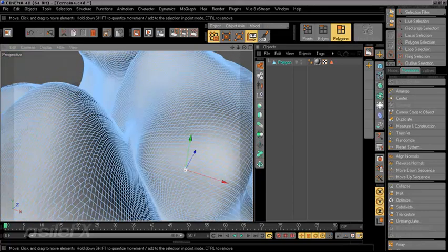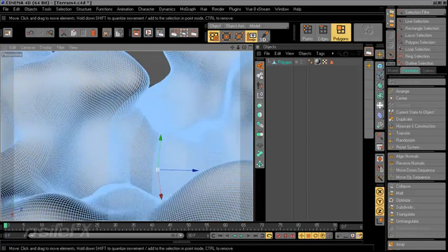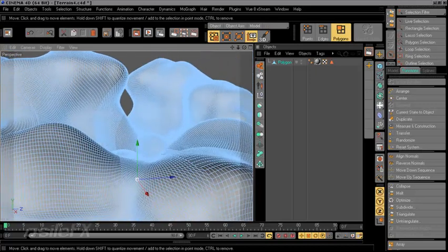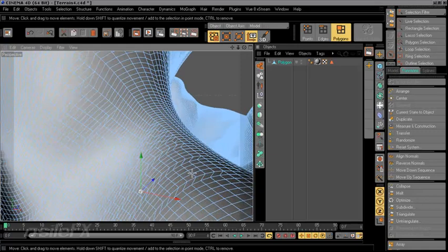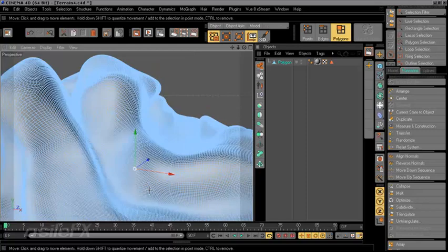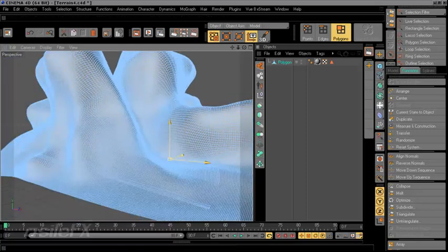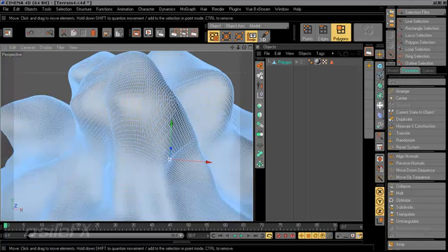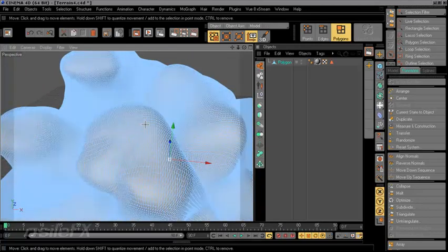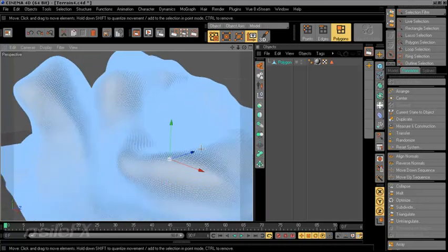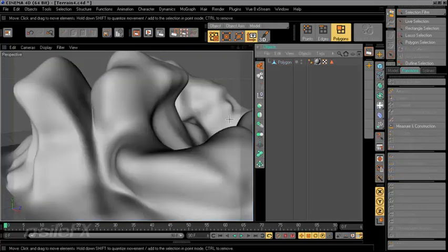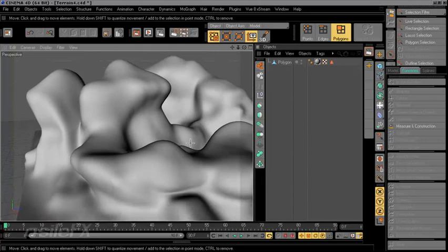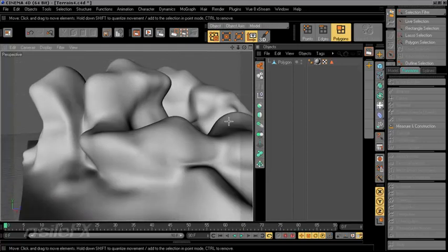Now the problem is the way that Vue generates the information, or the polygons, you're going to have a lot of interesting looking setups because of the way everything is divided, so you might not be able to get a good enough mesh to displace if the polygons are too erratic, but it is a possibility. Vue is typically used to working with its own type of object setup, so it might be easier just to stick with the triangles. Also, if needed, you could export that 2 million polygon version if you need a much better mesh.